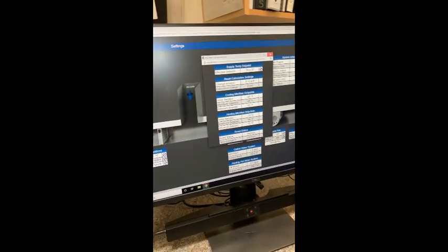And again, these set points can all be changed too, where in the future, if you guys wanted to, you could change it so that the initial set point was 55, the maximum was 55, and the minimum was 55, and it would just always give 55-degree air all the time whenever they went into a cooling mode. Then it'd be like the old school. And the valve does modulate to maintain that discharge air temp.